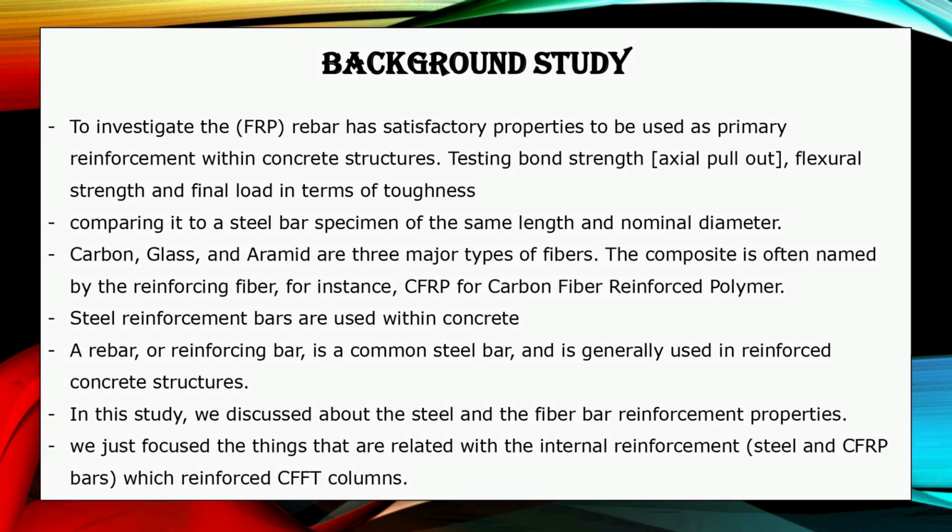For the background study, this research was to investigate whether a fiber reinforced polymer (FRP) rebar has satisfactory properties to be used as primary reinforcement within concrete structures. This was done by testing bond strength, which is axial pull-out, flexural strength, and final load in terms of toughness, and comparing it to a steel bar specimen of the same length and nominal diameter.